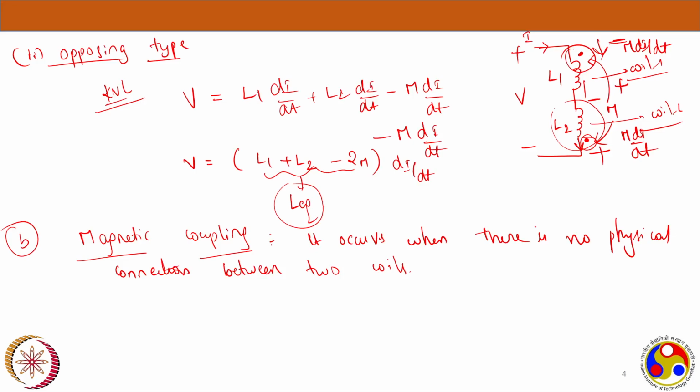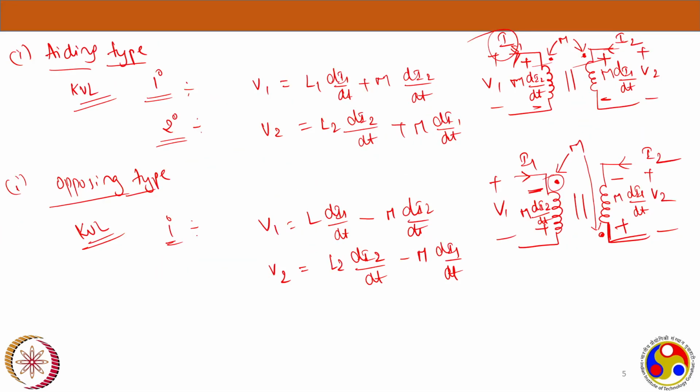And then we discussed magnetic coupling circuits and how a magnetic coupling circuit would look, and based on dot terminals, how the induced mutual inductance voltage will be. Just looking at this slide itself, we can say the self and mutual are aiding each other in the top two equations, and self and mutual are opposing in the bottom two equations, and that's how it is.